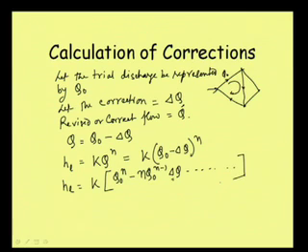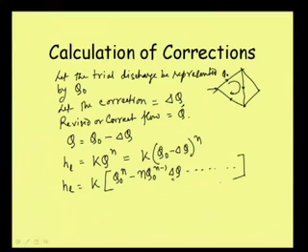K value represents everything: length, friction factor, diameter, combining everything, it gives a K value which represents that head loss is proportional to Q with this proportionality constant K. So, that takes care of everything. As we are assuming to some extent logically the value, we can consider that Q is very small. Of course, because we are not getting it explicitly, it will require some trial and error procedure.